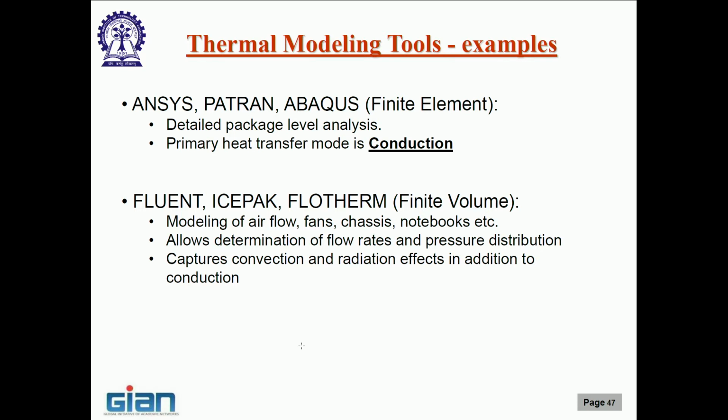Now Fluent, IcePak, Flowtherm, these enable you to solve for this. There is also Star-CCM+, there is COMSOL. Okay. They can all solve for the momentum and energy equations. All right. So if you want that kind of information, Patran, Abaqus is not going to. So what you are saying, ANSYS and Fluent, that is because ANSYS probably if you just need conduction analysis, Fluent if you need convection and flow analysis as well. Okay. Now Flowtherm, within Intel itself both Flowtherm and IcePak are used depending on the group. Okay.